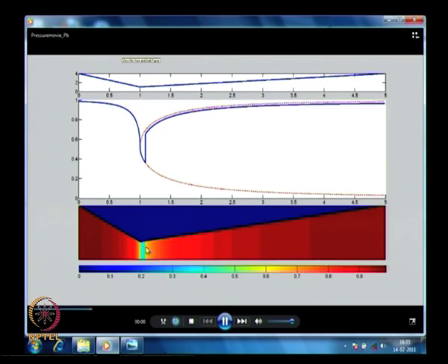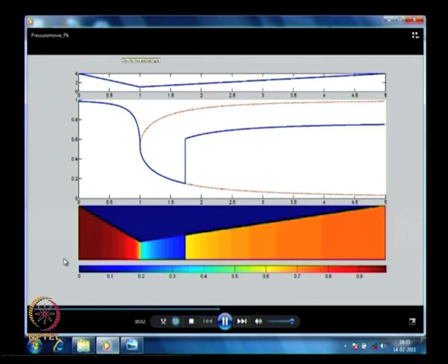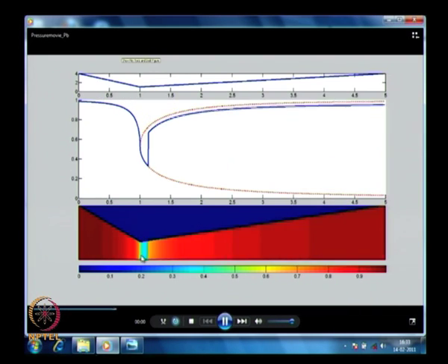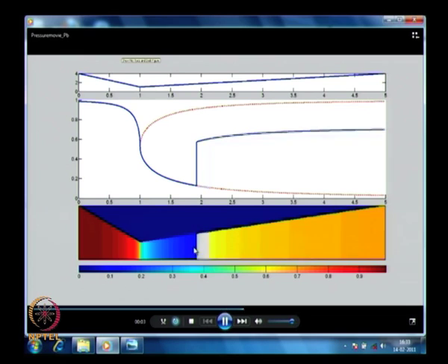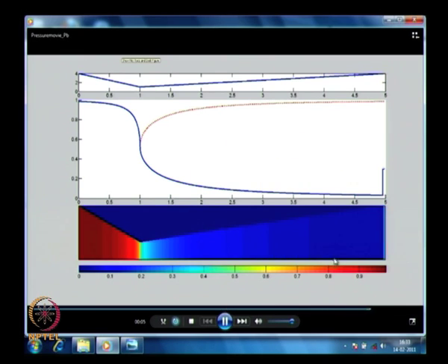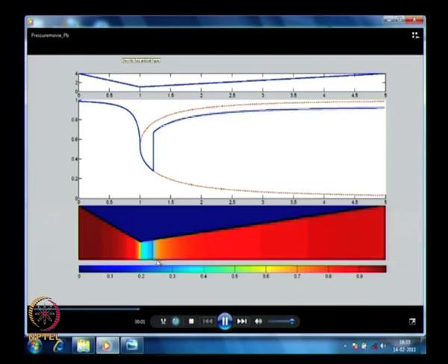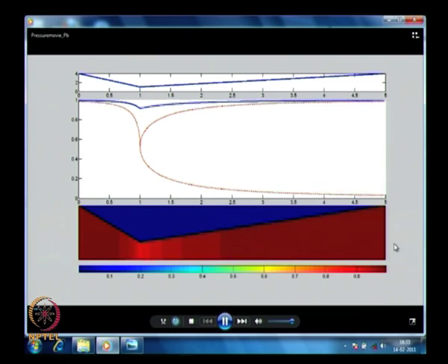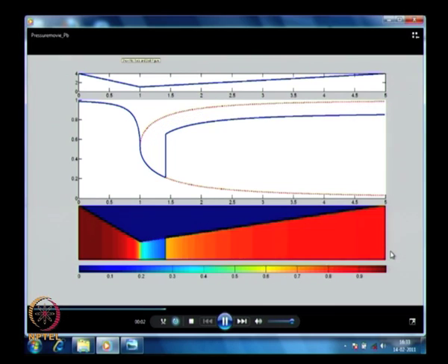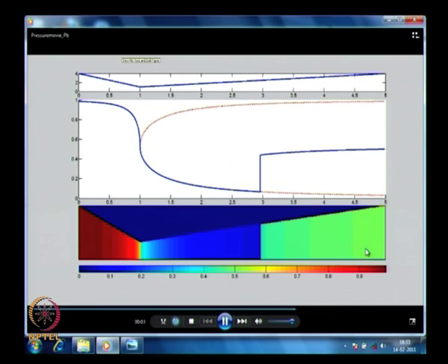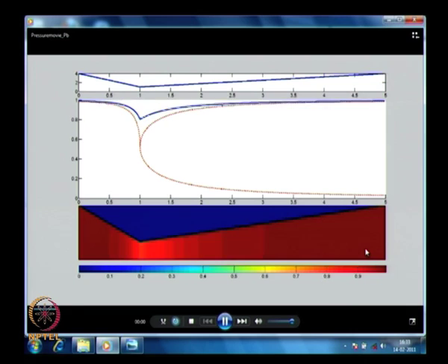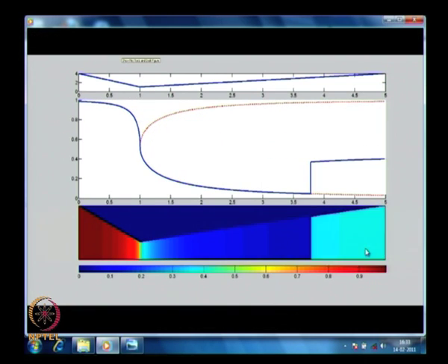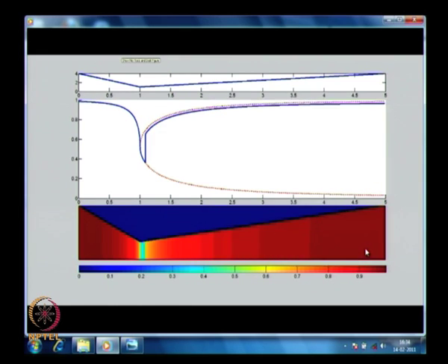We start with fully red, which is almost no flow, and then it is becoming more and more low pressures, the center becoming supersonic. That blue is all supersonic conditions, very low pressures, and the shock, this jump is the shock really, and that is moving more and more downstream, okay. This is one nice thing. We can of course plot other things like temperature, Mach number, everything similar, they all look the same almost, okay.